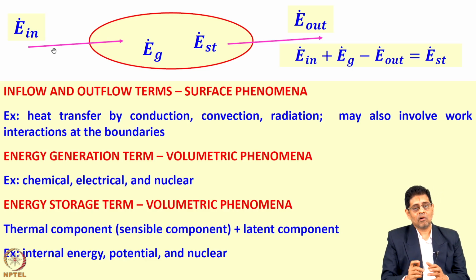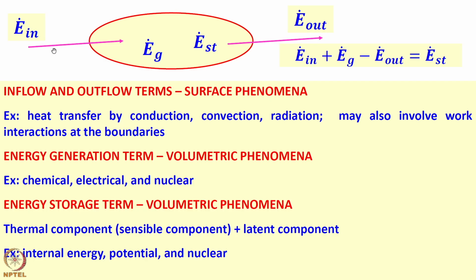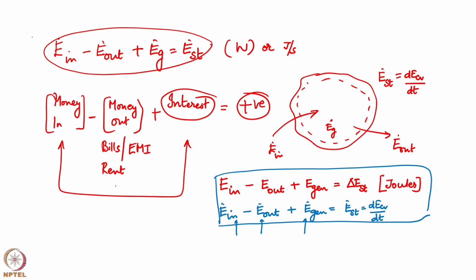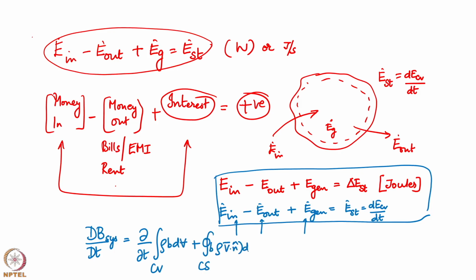That is transferred because of mass which is going to come in. If you remember your fluid mechanics, you had what we called the Reynolds transport theorem. If you have not studied it, it is okay, you will see it in convection also. This is your Reynolds transport theorem. This is an extensive property B, and this is the corresponding intensive property small b, and this is rho. This is your RTT, Reynolds transport theorem.